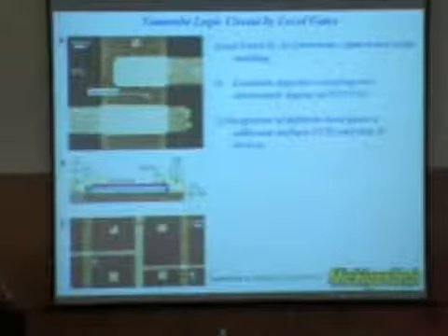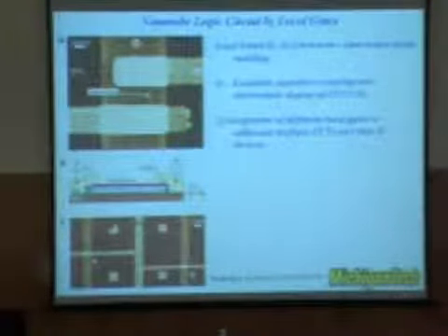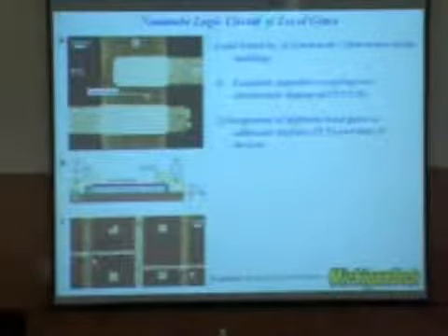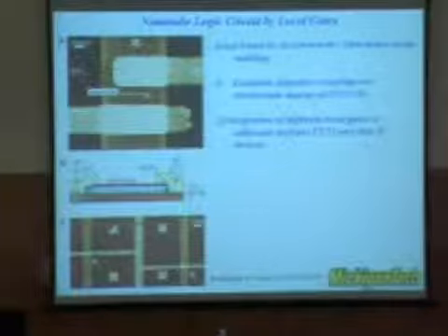And actually, a few months later, a paper in Science progressed much further from the idea that I showed you just now. In this case, it is using a local gate. The so-called local gate means each conduction channel here will have its own gate electrode. You can see here that you have an aluminum line, and each of these aluminum lines will have a very thin layer, about 2 nanometers thick, of native oxide. They will enable the switching of the gate of your transistor.